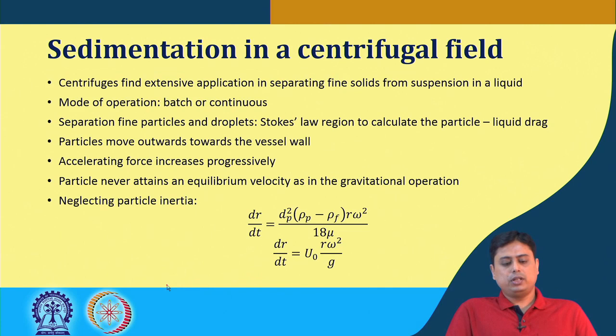So, the separation of fine particles and droplets, since this is warranted here, typically the calculation of particle liquid drag involves the consideration that Stokes' law region is valid. Then basically it compares the relative terminal velocity again, and this separation can happen.